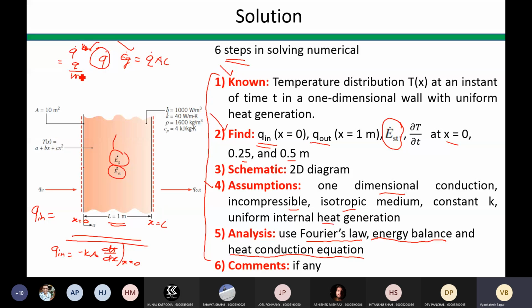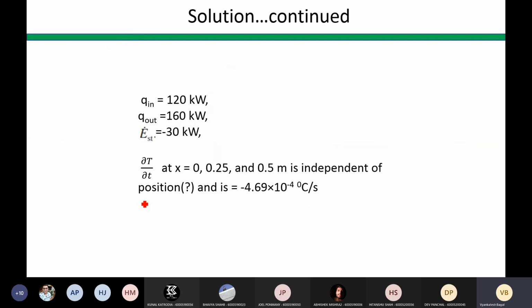So if I put the temperature gradient here, what I am trying to find out is Q in, right? So similarly, if I want to find out what is Q out, I may write the equation like this, minus kA dT/dx, and now this time I will write x equal to L. So evaluate this gradient at x equal to L, means at this face. Clear? Is it clear? So first of all, you must know what is the temperature gradient, right? And then you can find out this Q in and Q out. Now how to find out the temperature gradient? By differentiating with respect to x.